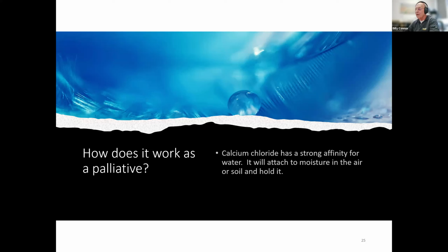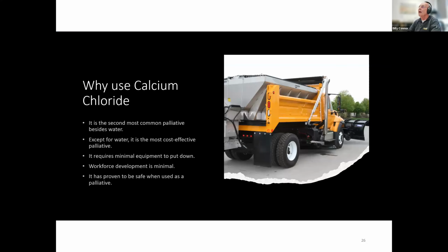And if you're in a really rainy climate, this might not be the palliative of choice because it's actually holding too much water, and it ends up being a little bit slimy for the traffic. So you want to be a little bit careful for those of you who might be, say, in Southeast or in the Kodiak area where it rains a lot. Calcium chloride is probably the second most common palliative besides water. So that's something to think about.